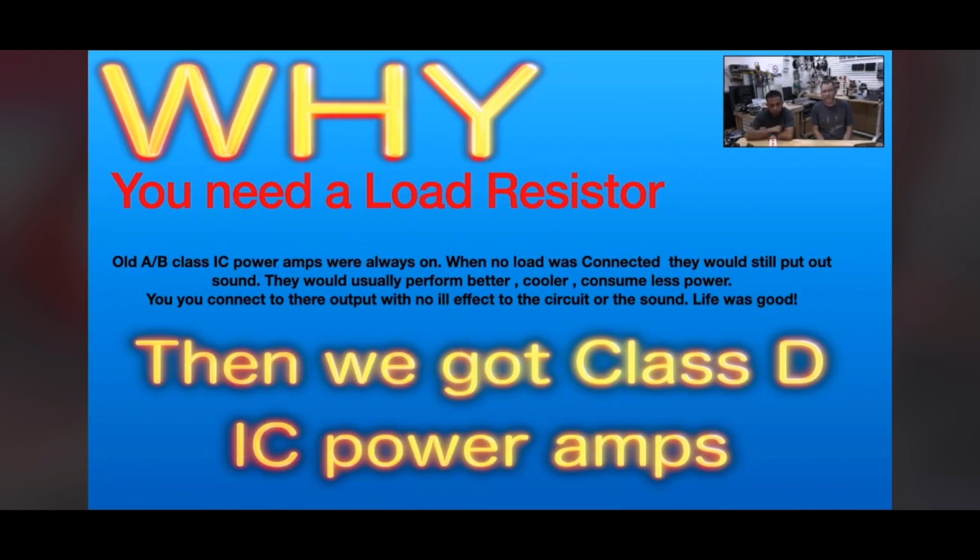Life was good. So think of it like this. If you had a factory radio and you grabbed two speaker wires off of it and hooked up your RCAs or your high level to low level or whatever you did, and you didn't do anything else, you never had a problem. It just worked. Because it was a Class AB amp, it didn't matter if there was a load on it or not. It would just work. It was even more efficient because that load wasn't there, so it would just go to nominal amounts of power. It wouldn't have to do anything.